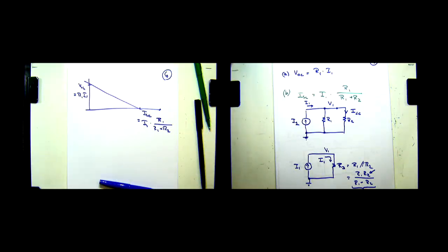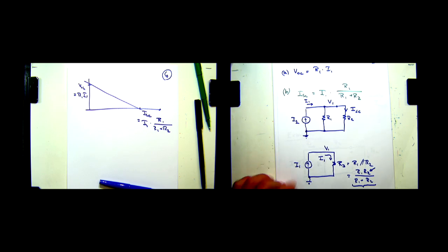We've seen voltage dividers, right? Voltage divider, two resistors in series. Now here, this could be called a current divider. The current I1 is going to be divided by R1 and R2. And how is it going to be divided? Well, according to this expression. In particular, the current ISC, that's the current that flows through resistor R2. That is going to be equal, it's a little bit like the voltage divider equation, right?